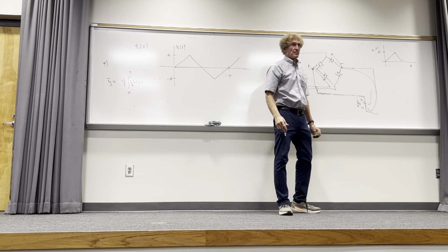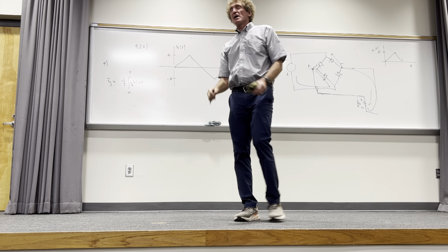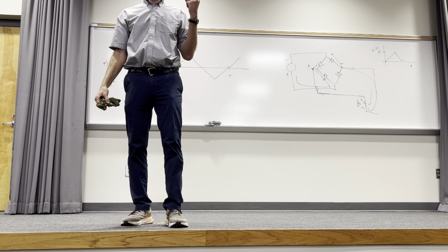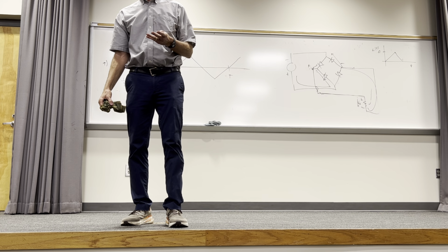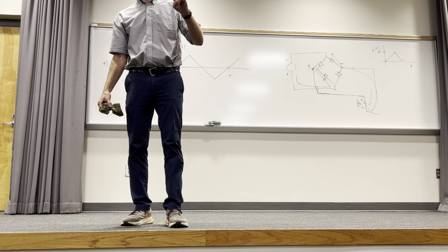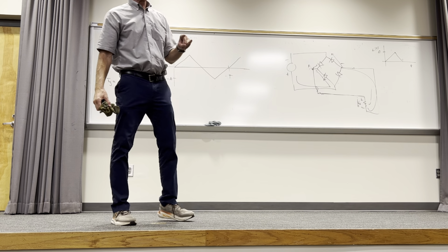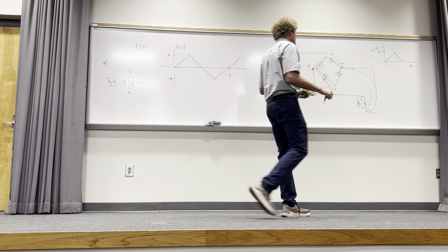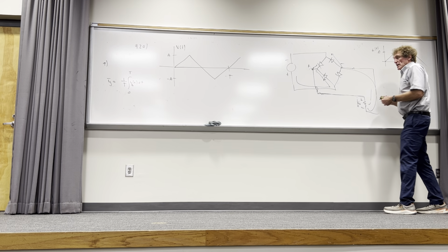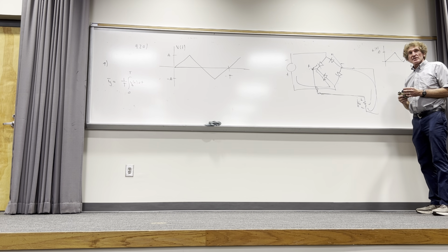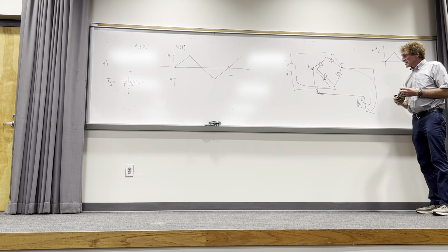Can you all see that? So two diodes are always on, and that's called a full wave bridge rectifier, and two diodes are always off. Except at the transitional point where it goes through an absolute zero, then nothing's on. Y'all follow? That's it. This is an ideal. So the waveform coming out of this would look like this. And if you're just a little more detailed, I think you can handle it from here.